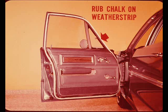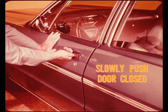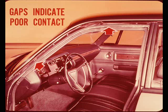The chalk on the weather strip transfers to the body door opening when the door is closed. With a good coating of chalk applied, hold the latch in released position, slowly push the door closed, and then reopen it. If you slam the door, the weather strip can momentarily flatten and distort the chalk print. Gaps or light traces in the chalk print indicate poor weather strip contact and give you an idea of its extent and the correction needed.